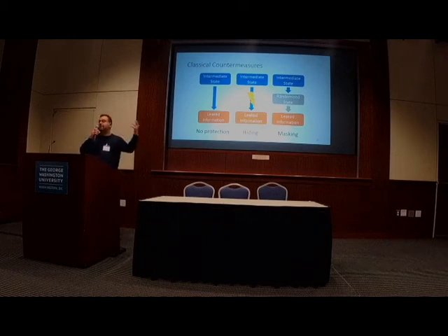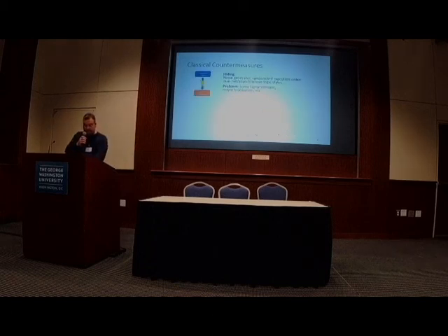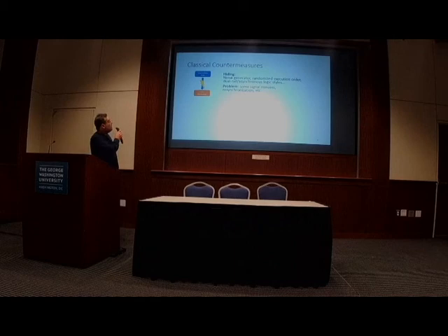These are classical countermeasures that have been used for over a decade now. In hiding, we typically use a noise generator of some sort, so heavy use of random number generators. Execution orders may be randomized. You can use dual-rail or asynchronous logic styles; there was a little bit of discussion yesterday on those.